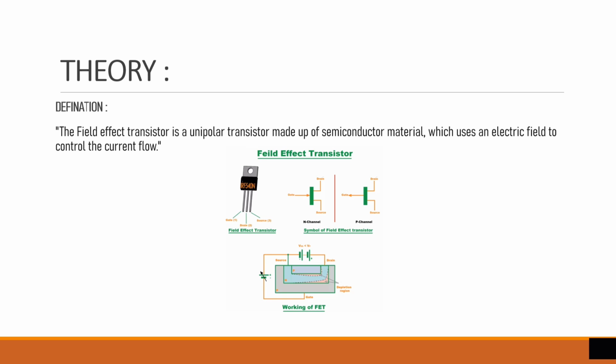The current always flows from the source towards the drain. A voltage is applied across the gate and source terminals, which creates a conductive channel between the source and drain. The electrons or holes flow from the source to drain in the form of a stream through the channel. There are several other things involved in the working and function of a FET according to their types.